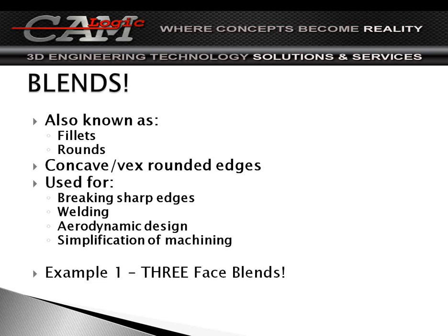They're used in aerodynamic design in order to smooth out parts, so you don't set up either drag pockets or any interference. And then also to simplify machining. If weight's not a constraint, then to smooth it out, you could use less precise tooling, and you can also machine quicker. So blends and fillets have multiple purposes, even beyond what I just explained. But that's just the basics of engineering. So let me go to an example.